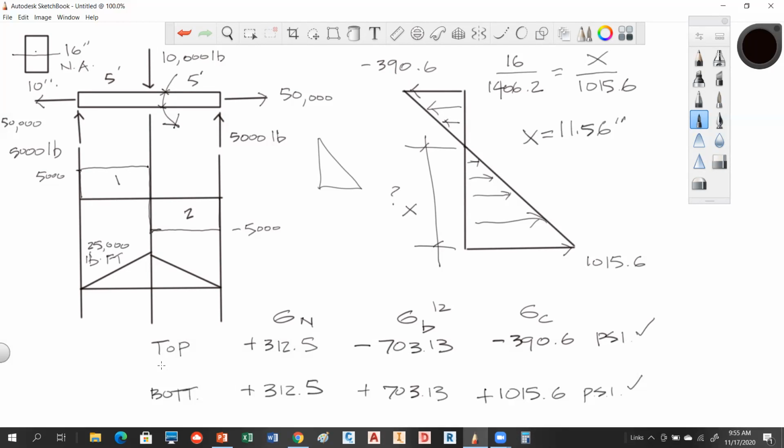So this little chart kind of does all of your work once you get all your numbers, but notice this is a pretty good step process. You had to calculate your axial stress, you had to go through a shear moment diagram to get your maximum bending, then you calculate your bending stresses, and then you have to assign those values. We're going to be working through these problems, but I'll tell you what, this actually isn't that tough to do, okay? So anybody have any questions?